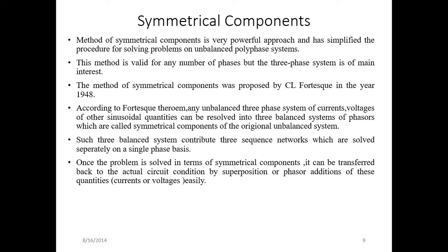So what is meant by the symmetrical component? The method of symmetrical component is a very powerful approach and has simplified the procedure for solving problems on unbalanced polyphase systems. This method is valid for any number of phases, but the three-phase system is of main interest because whenever we do the unsymmetrical fault analysis, mostly we consider the three-phase system. This method of symmetrical component was proposed by C.L. Fortescue in the year 1918.